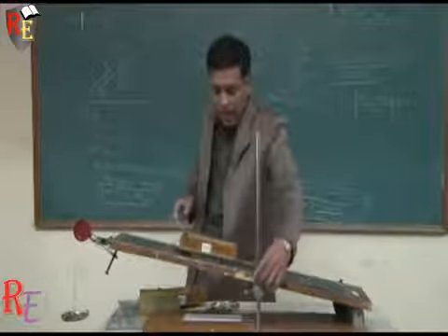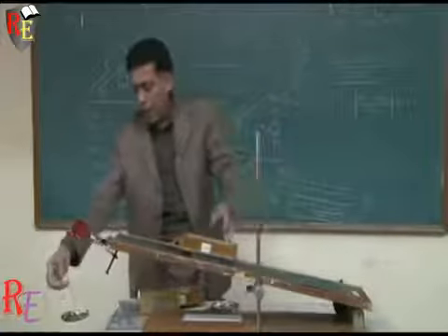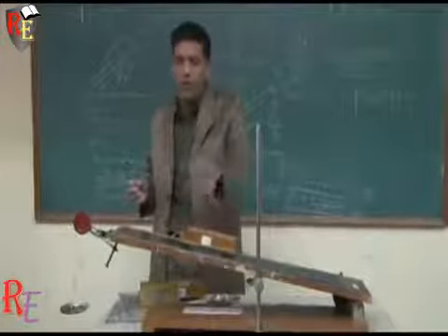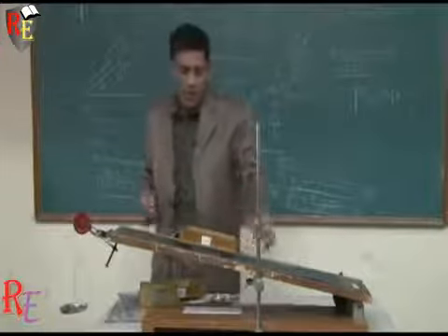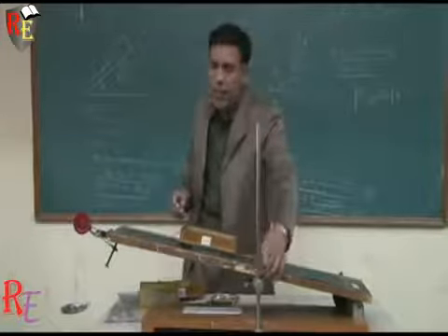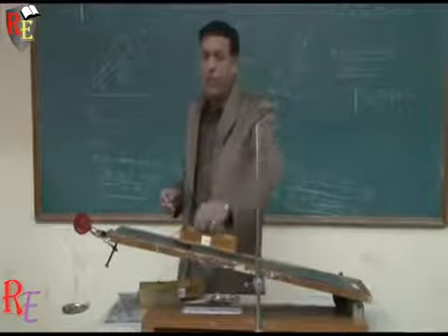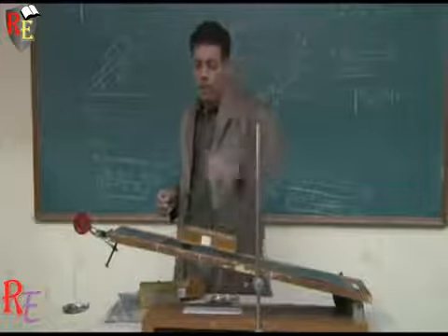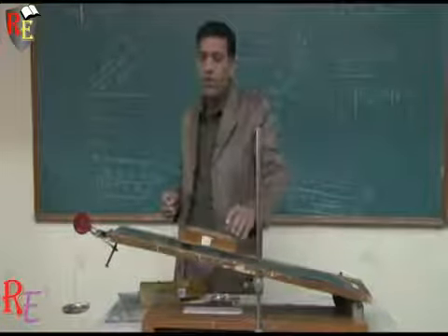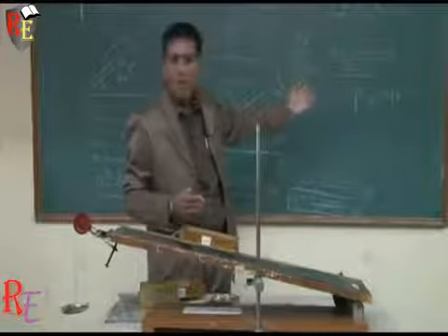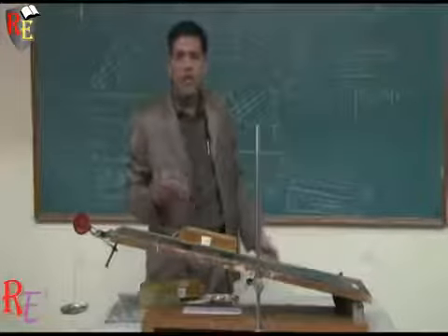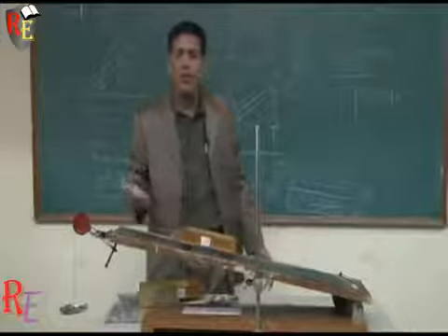The first is that we are changing the angle of incline and we are applying the load on the pan so that the block is just on the verge of the movement. That is the first method. The second is that we are setting the incline at a particular angle, but we are changing the weight of this block by adding or removing certain weight to this block. Okay, and we would find out the percentage error for the different sets of readings, and the average value of the percentage error would be found out. Thanks.